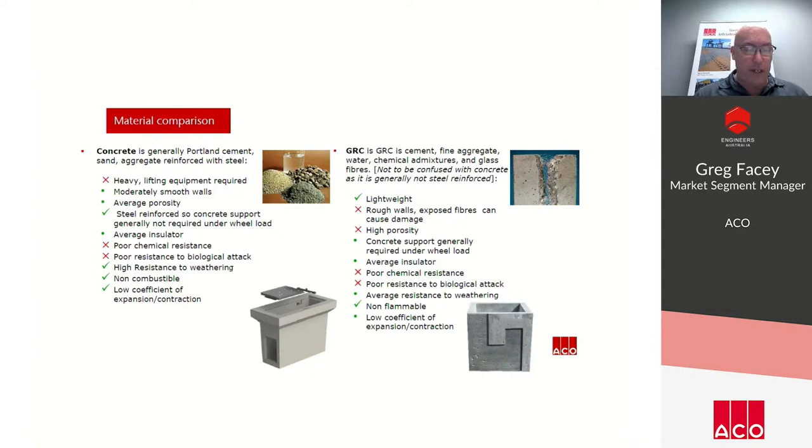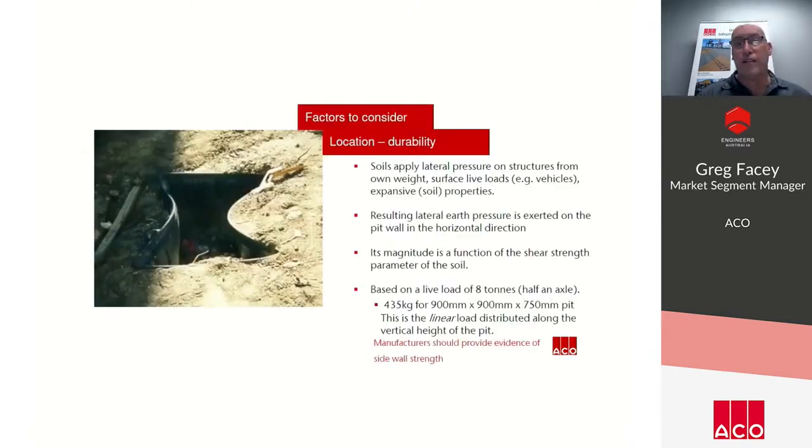It's also worth noting with GRC, it's prone to deterioration, particularly in alkaline soils. Therefore, GRC pits require regular maintenance and in some cases are susceptible to early failure. However, we do need to consider the location in terms of durability, because adverse ground conditions may require an increase in these dimensions or the addition of reinforcement. If in doubt, engineering advice should be sought.